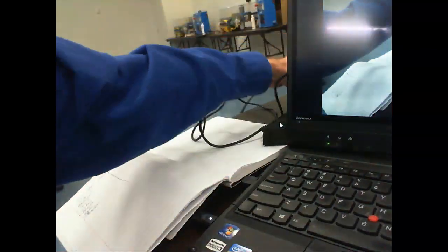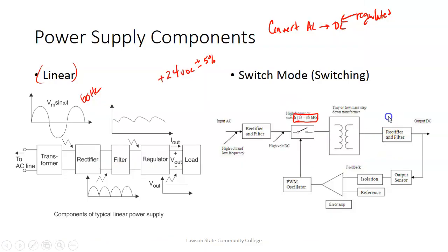So the advantage of switching power supplies is they're more efficient than linear power supplies, but they're almost impossible to fix, and they're hard to troubleshoot, guys. I've tried to troubleshoot them, and this feedback loop right here, everybody's set up to cause it to oscillate, but it don't oscillate, so we got big problems. But these guys are starting to dominate, because most of the time when these power supplies go out, we just replace them. These guys, though, we fix them. So all our trainers use these power supplies right here.